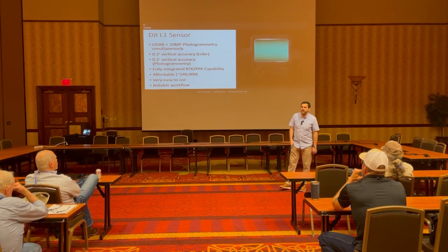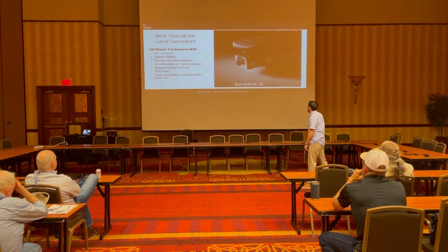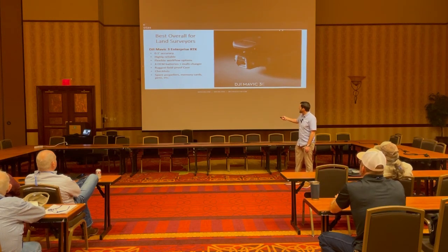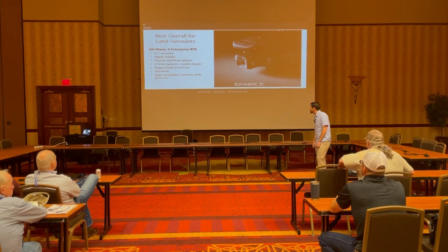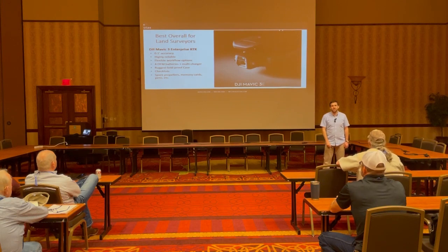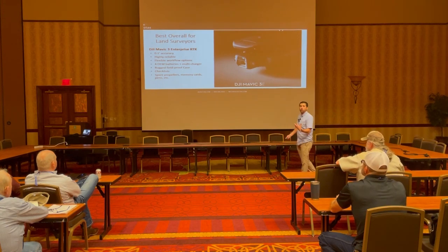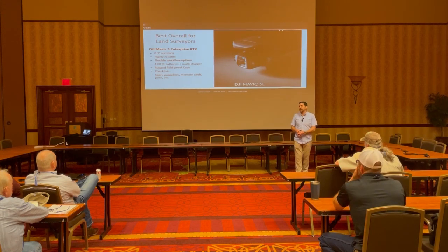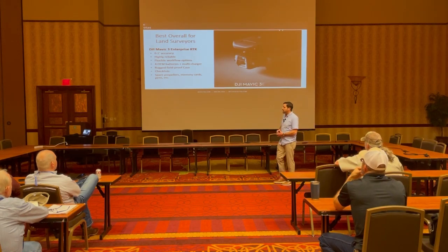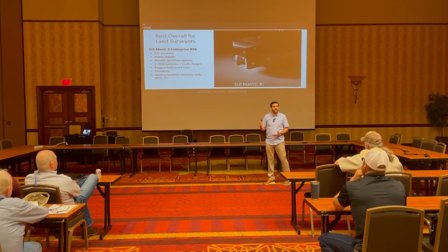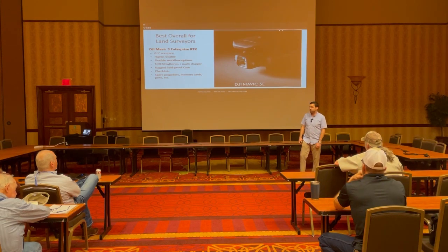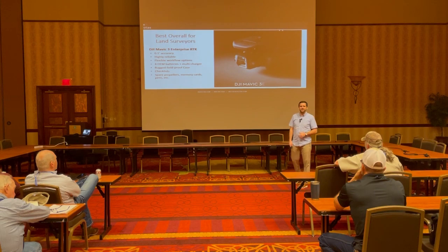So this is actually our favorite LiDAR sensor out there. But like I mentioned before, our favorite overall drone for land surveying is going to be a photogrammetry-only drone. Mavic 3 Enterprise RTK. It's cheap. This is becoming the workhorse drone for surveyors out there because it is cheap enough at, again, about $10,000, $12,000 all in, cheap enough to have one in every truck, fly a site when you need it, really easy, really unobtrusive, and very, very common. Quite frankly, super boring. Again, good thing for me.